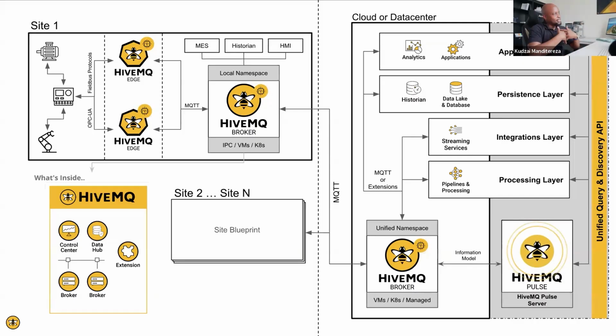But basically what you can see from this is that you're really moving from a situation where you need to subscribe to 100, 200 MQTT topics to get the data you need, and this data is being generated dynamically. Here you're getting the data from a governed namespace that exposes a query layer. So you can ask for the data that you actually need in the format that you need. You don't need to subscribe to hundreds of MQTT topics and then build the logic to build your data-driven application.